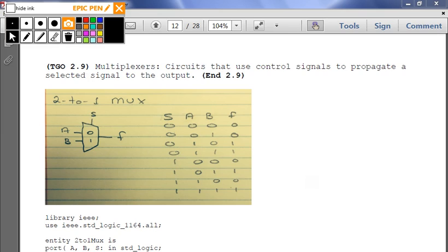So you can go enable is 0, and then input is 0 or 1, and both of them are just Z, right? And if it's 1, what is that going to be? Yeah, they're going to match. So now you've derived the truth table by understanding the thing. Same thing with the 2-to-1 multiplexer.